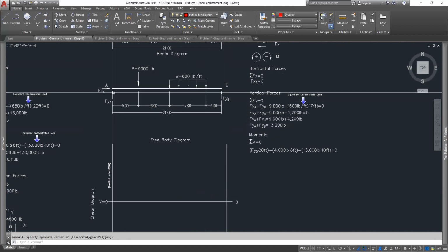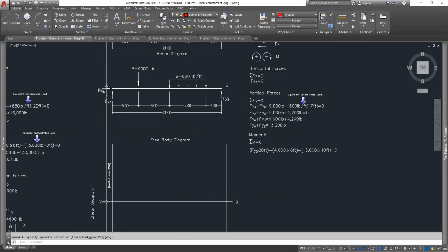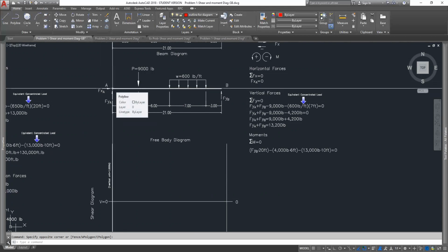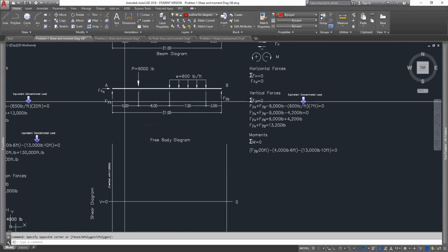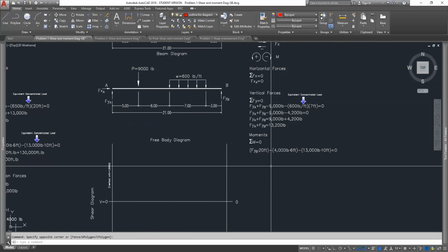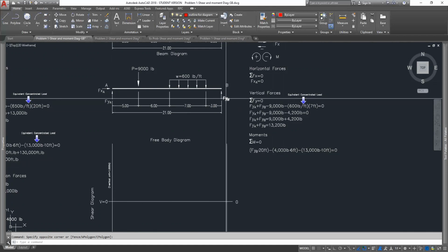Now you have these forces in here, but we're taking the moment right around that point. So where you're taking that moment, you do not take those into effect. That would be 0 at that point because it has no distance. It has no value to it at that point. So let's start with our equation on the moment equations. So we're going to start with FYB.